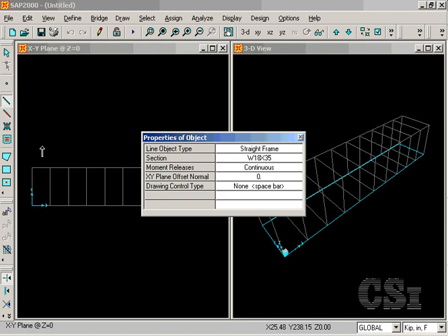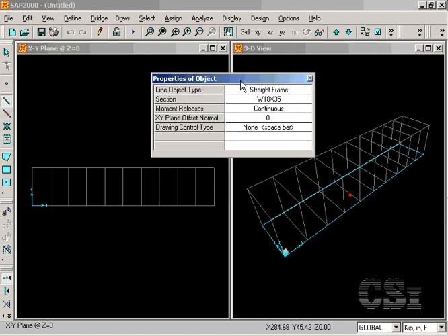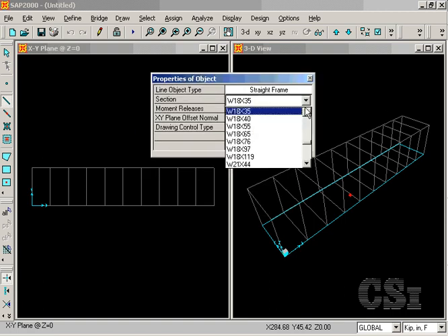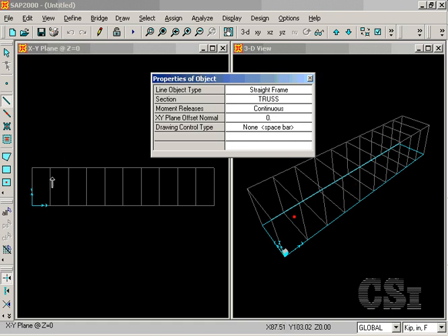We are going to draw the truss objects and want the program to assign members from the truss auto-select list we created. Start by drawing the bottom chords. Click at the beginning and ending points to draw a single object that represents the physical member. A right-click will stop the drawing action, but leave you in the draw mode. Also draw the first cross object. Hit the Escape key or Select button to leave the draw mode.